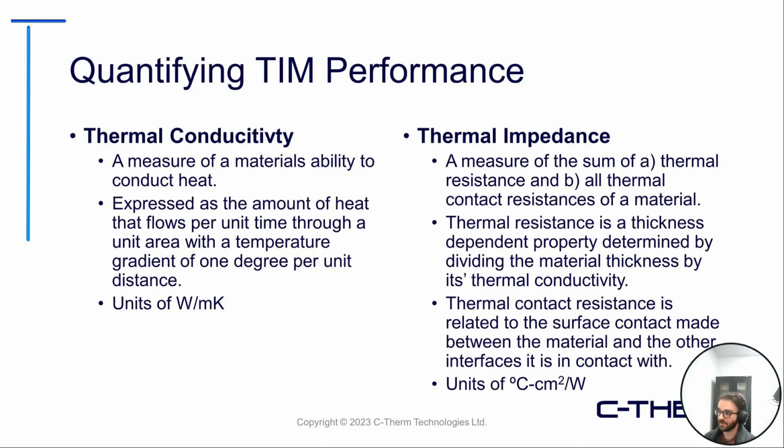This is another metric used to quantify TIM materials. Thermal impedance is a measure of the sum of a few things. First off, the thermal resistance of the material itself, and secondly, all thermal contact resistances of that material.